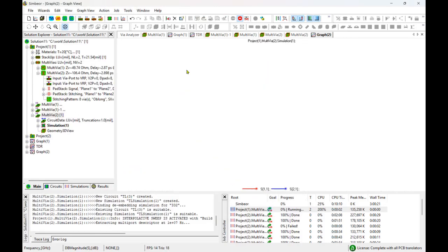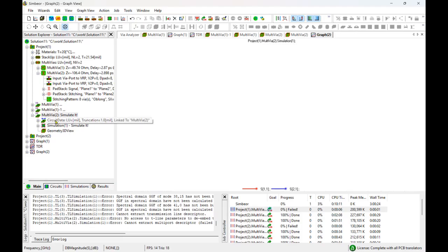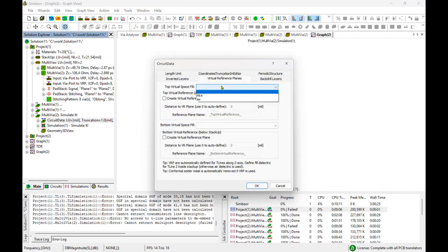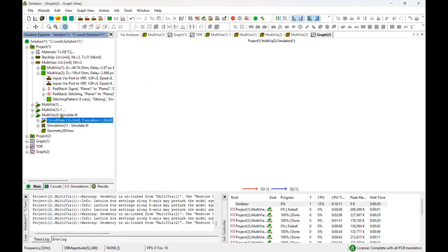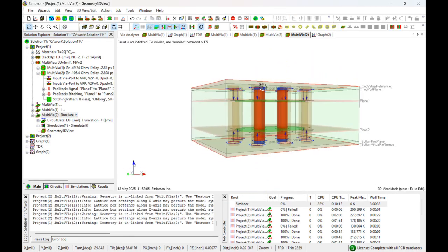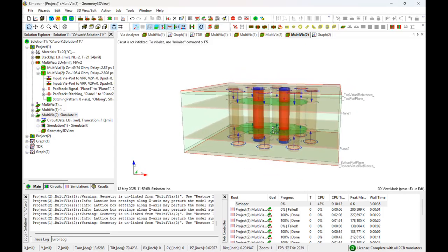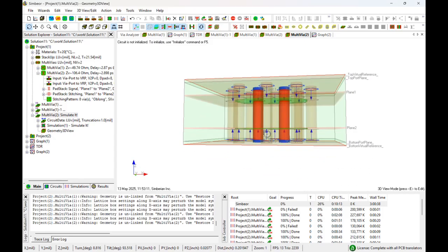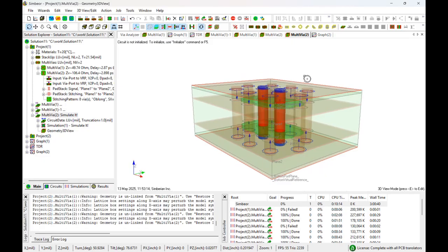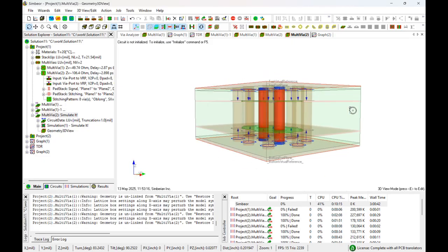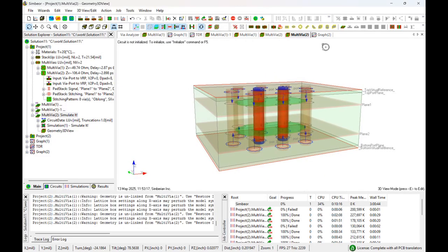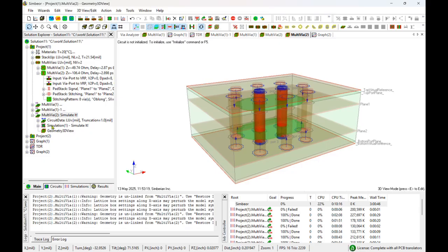Oh, before running the simulation, one more step is to put the FR4 fill on the top and bottom. And right here, every port or I/O is de-embedded to the plane level. You can see those arrows here. That's the idea. So essentially put some ports, de-embed them, and have just the middle section. And that's it. Now I can run it,